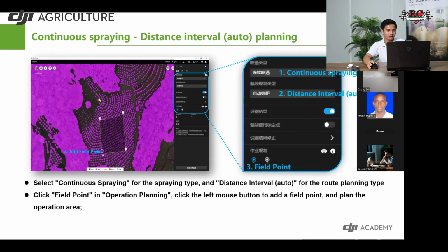What I want to do, let's say this farm I want to spray, the first thing I do is the survey. So walk around or maybe drive around, then I have an idea which area I will take off from for my agras. Then I put a carpet, something visible, black, 2 carpets at each spot. If I plan to take off from 3 spots, maybe I will need 6 carpets. I put 2, 2, 2, and then I map. Before I remove the carpet, I put some stick or anything I can see the next day when I come. So I use that kind of fixed point for accuracy purposes.